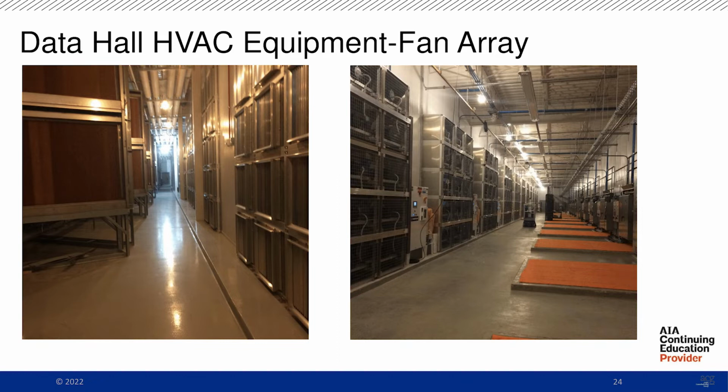All right, the fan array. This is where I'll get excited now. Kind of looking down, on the left side is the inlet of the fan array. I want you guys to pay attention to how this ECH module right here goes into the fan array, and then this is the outlet side. These are your supply shafts. They just have construction media over them right now, so normally it's just grates going down. Like I said, I think your airflow monitoring station is about 60 inches down, somewhere between 6 to 8 feet.